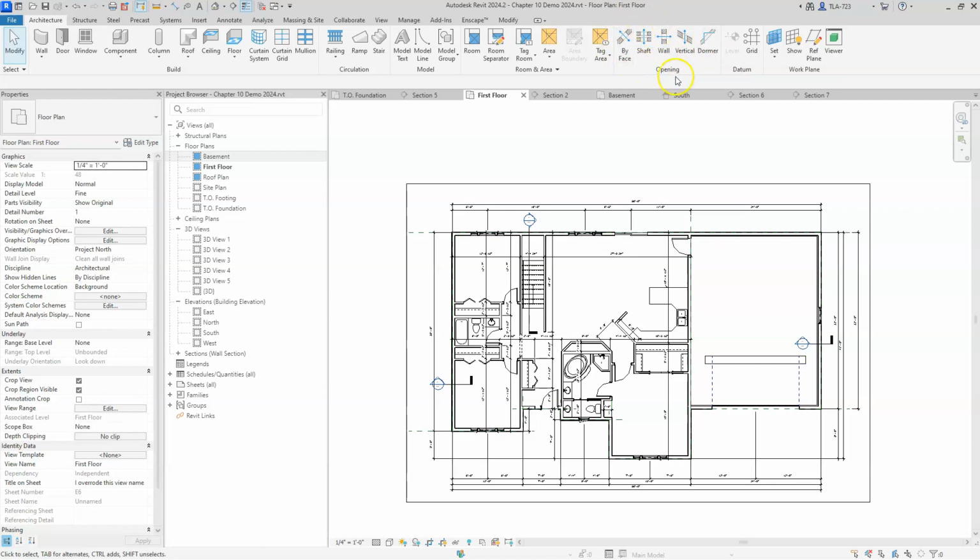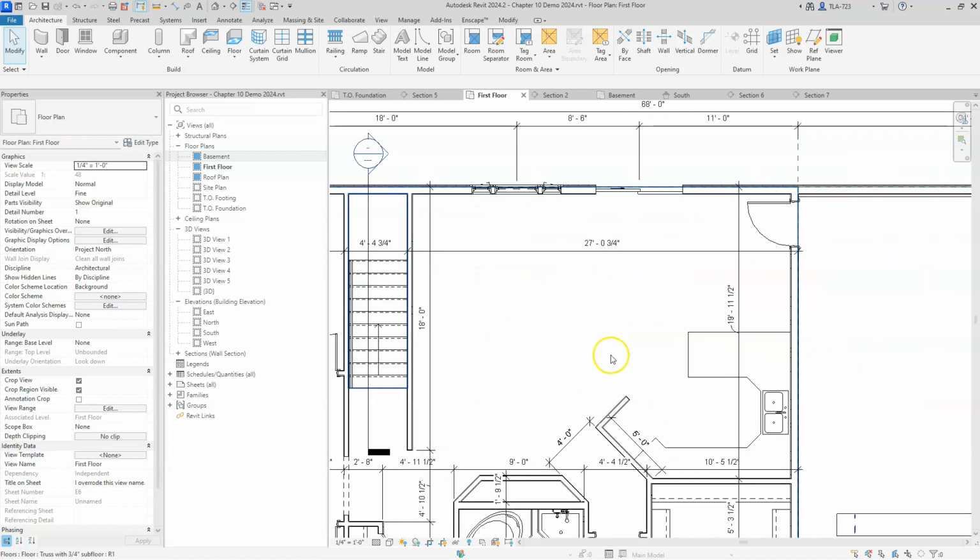And there are a few different ways that you can create a shaft opening. You can create it through a sloping roof. You can create it on a face at any direction, or you can create it perfectly vertical. And a shaft is sort of like a void space. It's not really a physical object. It just exists to carve out portions of a horizontal thing, right? So if I wanted to, for example, put an elevator in the middle of my kitchen here, I could create a shaft opening to remove that geometry. It doesn't actually cut a hole in the floor. It just creates a temporary hole in the floor. So let's go ahead and just do one real quick.